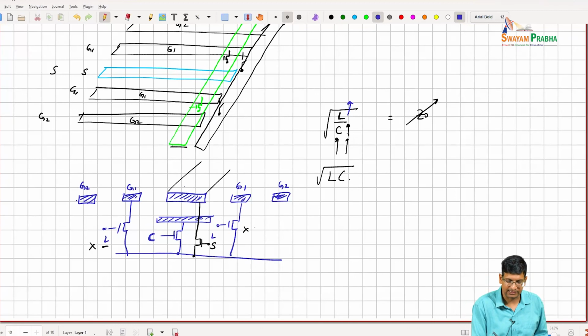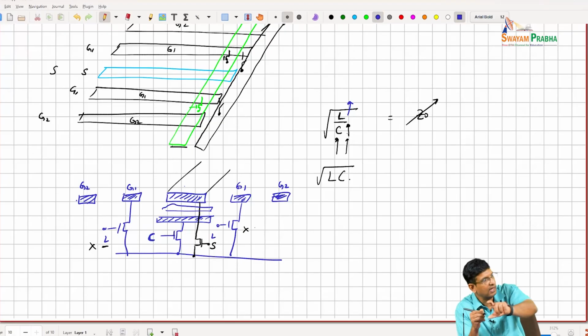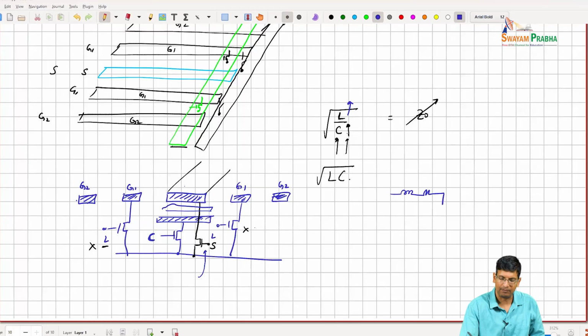Because you have multiple of these C's, right? Which are located at different points along the chain. And what they find is that depending upon these states, the loss starts varying. So in order to equalize the loss, they introduce this S switch, which is basically saying that I'll make the L coarse variable, I'll make the C more fine variable, but I will also take this part and make this variable periodically, right?